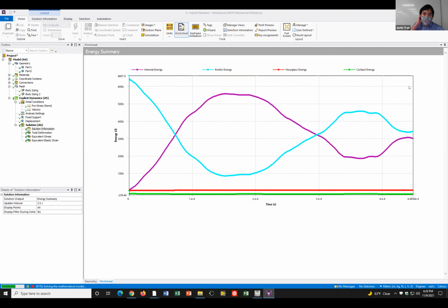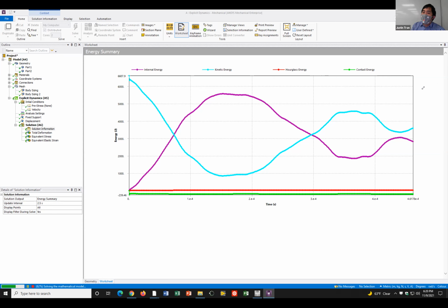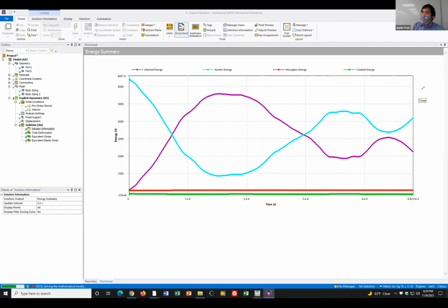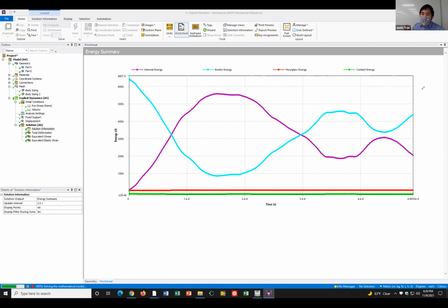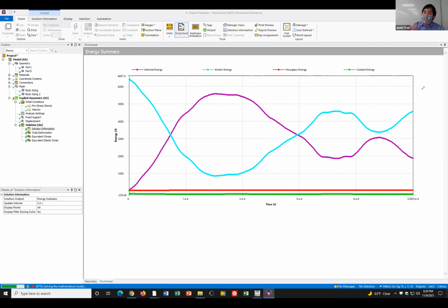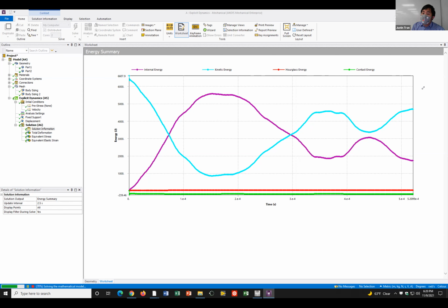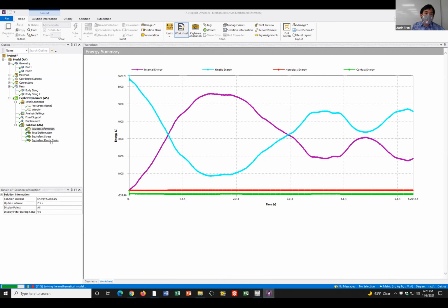And so, when you look at the total deformation, you might see the whole car having huge deformations. But that's not really true, or it is true, but the reason it's true is because the car actually has some velocity and it's moving away from its initial position. Okay, and so if you want to get a true sense of deformation, the same way that we got from static simulations, you would have to look at the strain instead.